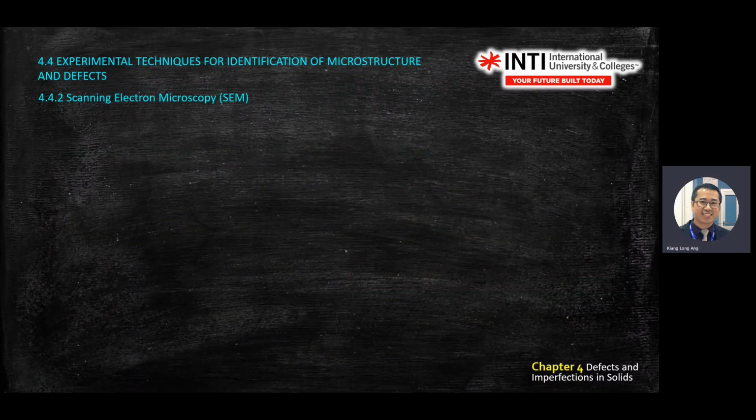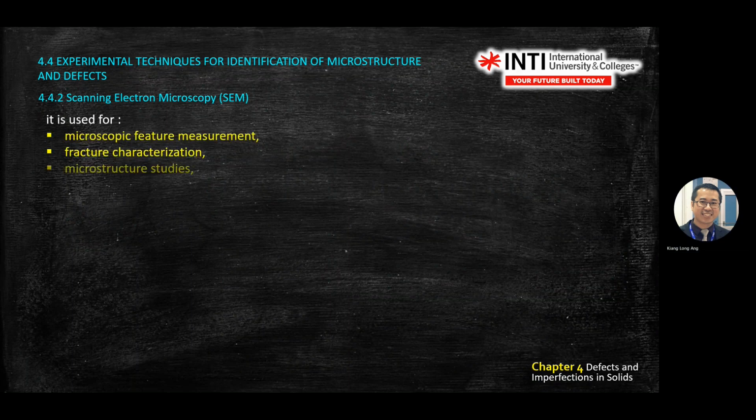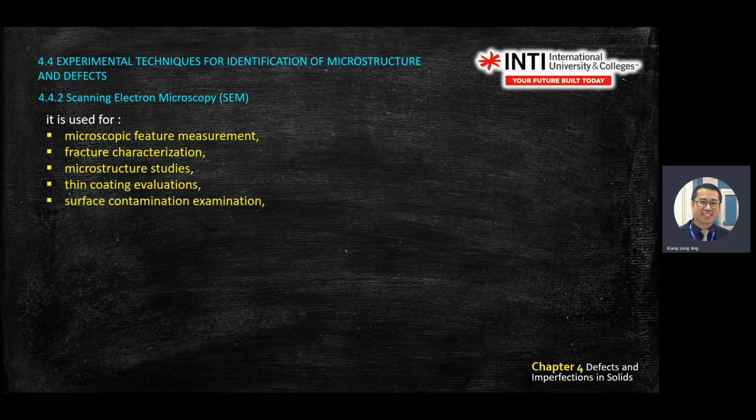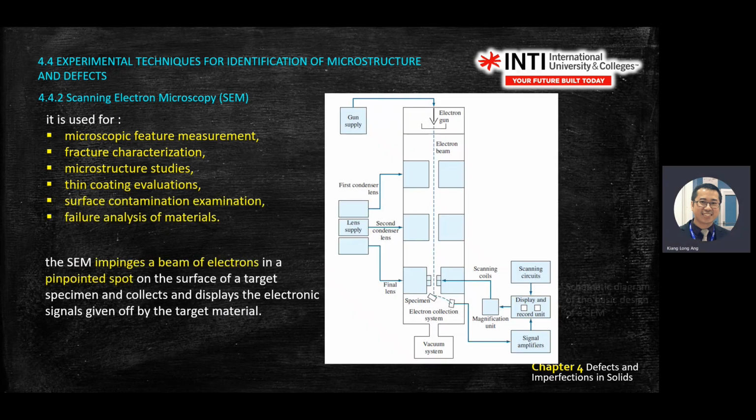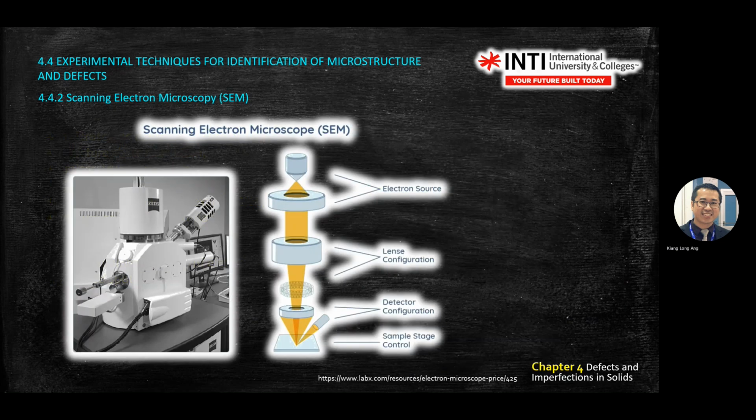One instrument we use in material science experiments is called SEM, scanning electron microscope. The rest you read. So it looks something like this, very expensive. Minimum will cost you 1.2 million and above for one instrument like that. And you need a strong foundation that can absorb vibration when you conduct experiments, because all these use X-ray, very sensitive ray. Your foundation must fit with an anti-vibration mechanism.